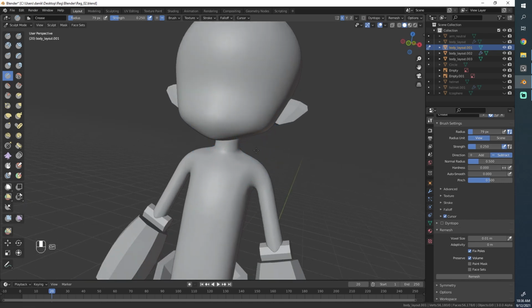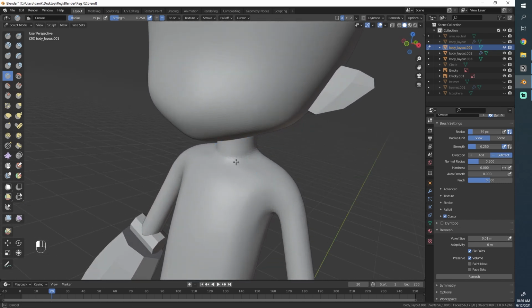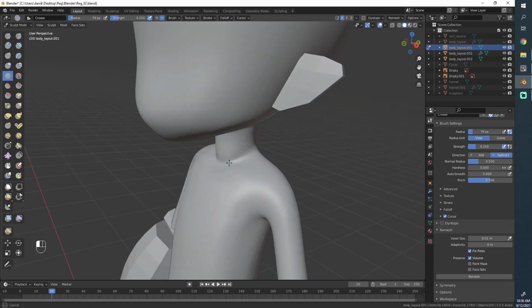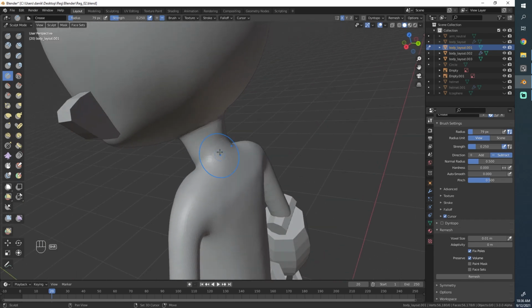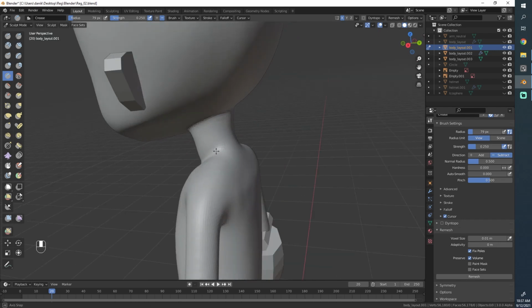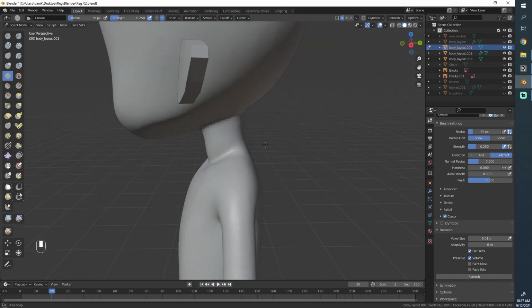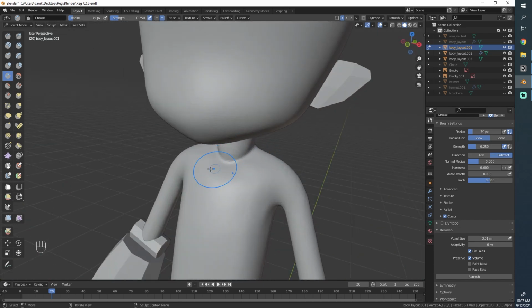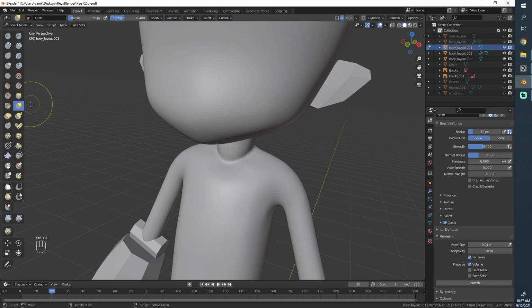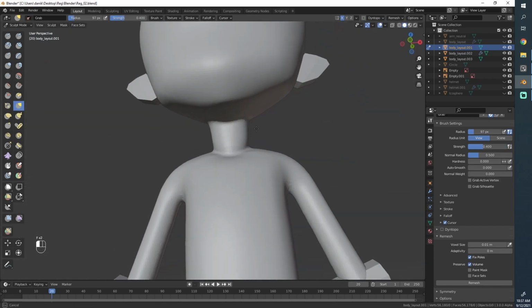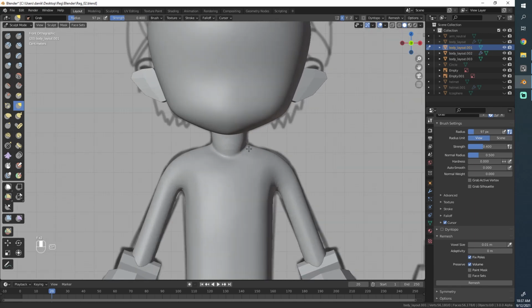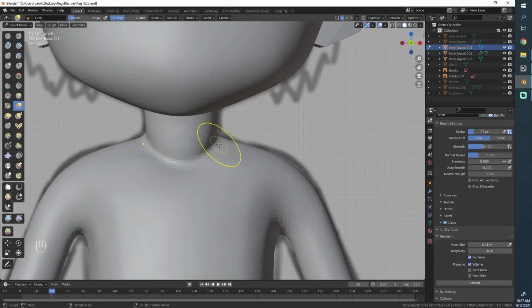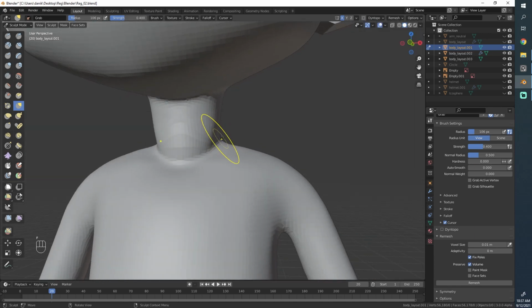You can also, for now, since we don't have the additional detail now, go down here and brush a bit over here. Don't brush in the back too much. The skin is supposed to be quite smooth here in the back, but in the front feel free to give it a few strokes to make this one sharp as well. And if you need to adjust the proportions a little bit, just use the grab brush, or the move brush, or whatever it's called in your sculpt tool.